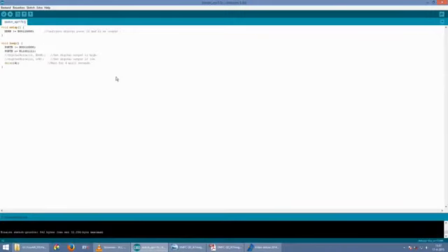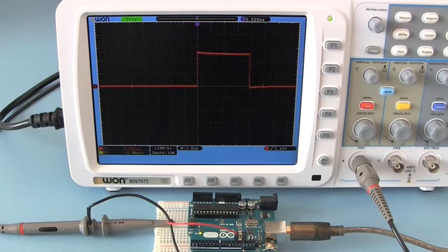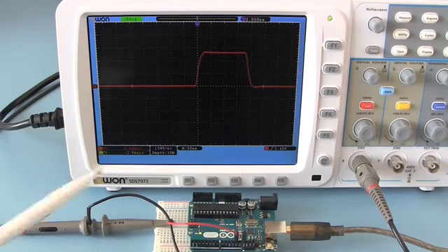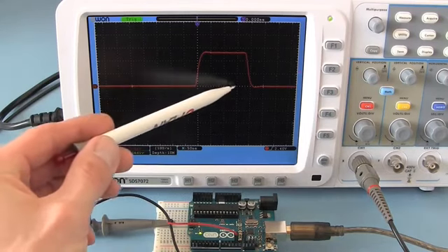We already know that the digitalWrite command uses 942 bytes. When we compile the code with the port B manipulation line, the size is further reduced to 680 bytes. So with a few simple steps we reduce the size of the sketch tremendously. Now let's upload the code and have a look at the scope. As you can see, the length of the pulse is reduced from 4 microseconds to 200 nanoseconds. I think this makes a pretty big difference.